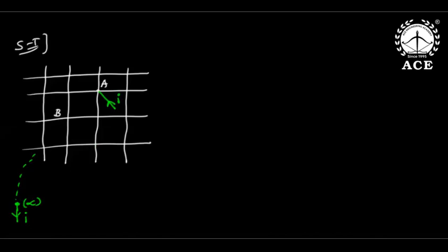Now because path resistance in all paths is the same, I can do the current division rule. So this I is coming, it will divide into 4 equal parts. This is I by 4, I by 4, I by 4, I by 4. But again, after this, coming here I by 4.